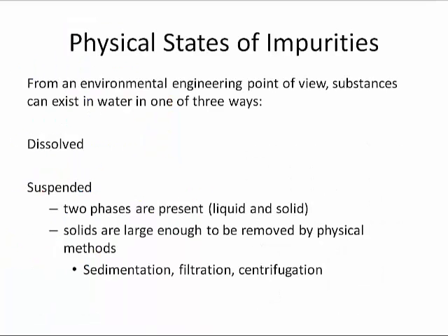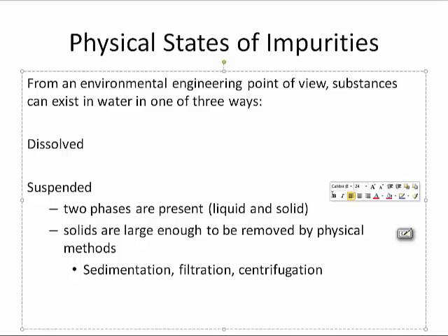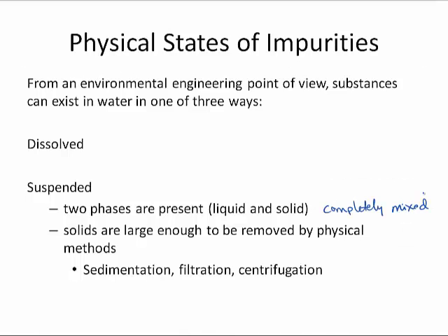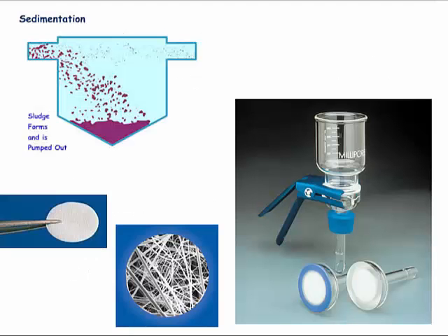The second physical state we'll discuss is suspended solids. In a suspended situation, you have two phases that are present but are completely mixed. You have a liquid and a solid phase. These can be completely mixed. When the solids are large enough to be removed by physical methods, we can apply sedimentation, filtration, and centrifugation.